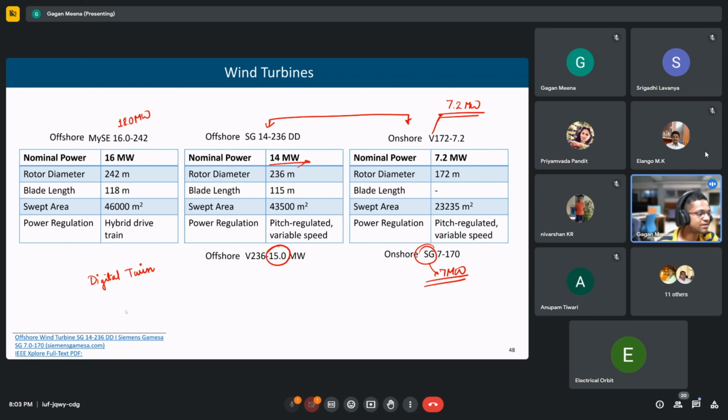What happens actually right now, the policy is that whatever the renewables are generating, they are allowed to feed it into the grid depending upon what their schedule is. You can't do it all the time. The utility, typically for these bigger power plants, will have control. So they are given a one day schedule. They will say that within a 10-15% margin, let's say one wind farm is saying we will produce around 1 gigawatt plus minus 10%. If they go beyond that, then they will be penalized.